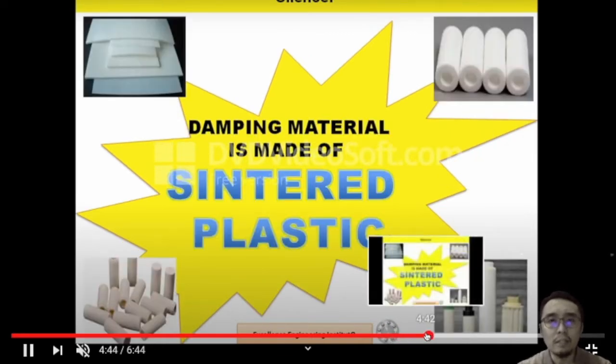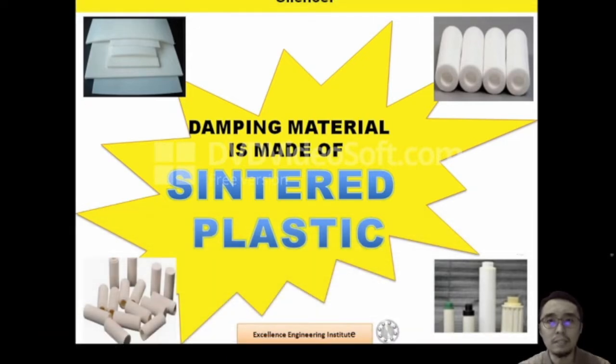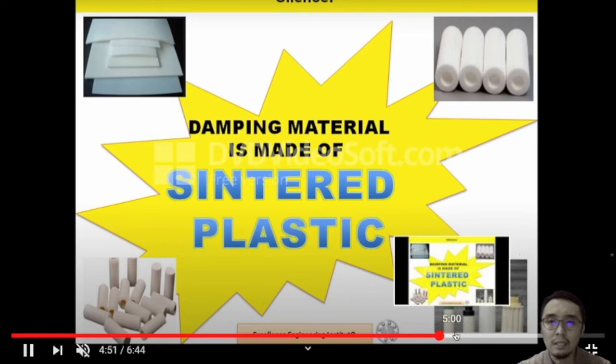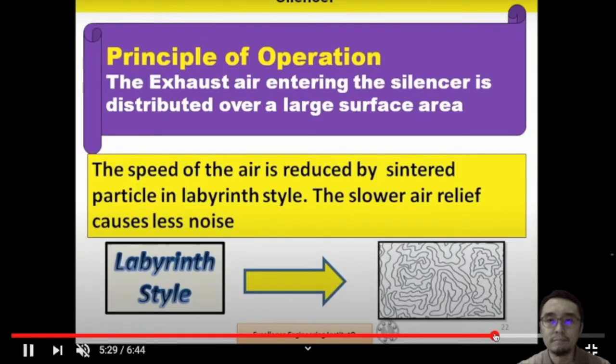You would have a damping material, and the material is made from sintered plastic. Okay, and how does it operate? Basically, the material will absorb the noise caused by the high pressured air. As explained here, it is distributed over a large surface area, so the speed of the air is reduced by sintered particles in a labyrinth style. So the material will absorb part of the noise.